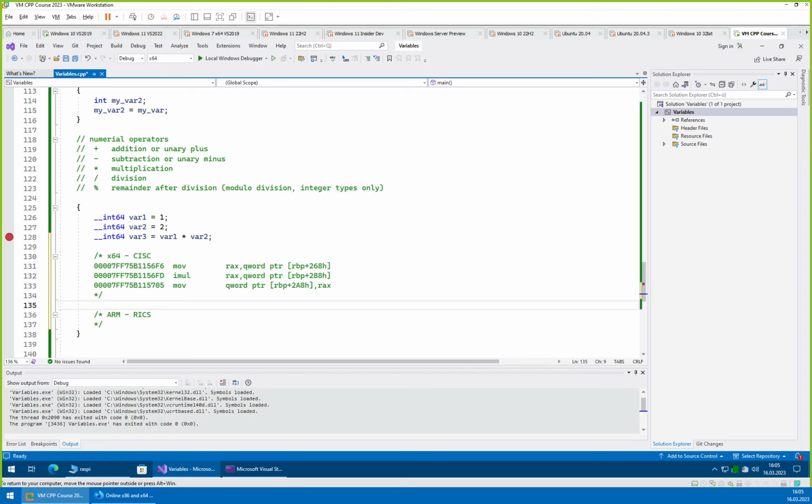And the main obvious difference between those two instruction sets from an ideological standpoint is that in the complex instruction set you can have instructions that do something with registers and with memory, while in a reduced instruction set the only operations which can do something with a memory location are operations which load values from memory to registers or from registers to memory. The result of this is that, except for those very few opcodes, the whole rest of your opcodes always operate on registers only, which allows for a somewhat more efficient implementation.